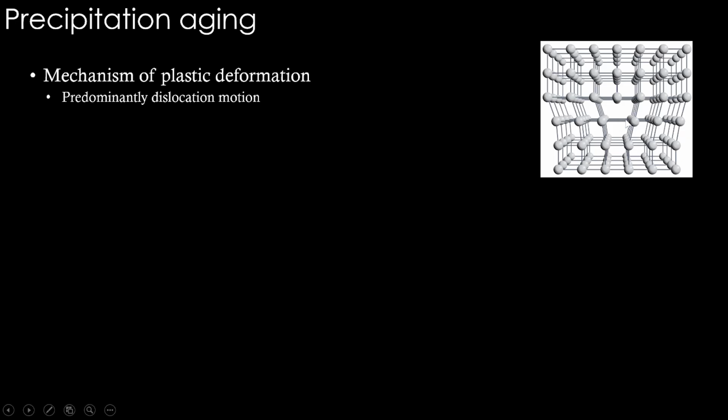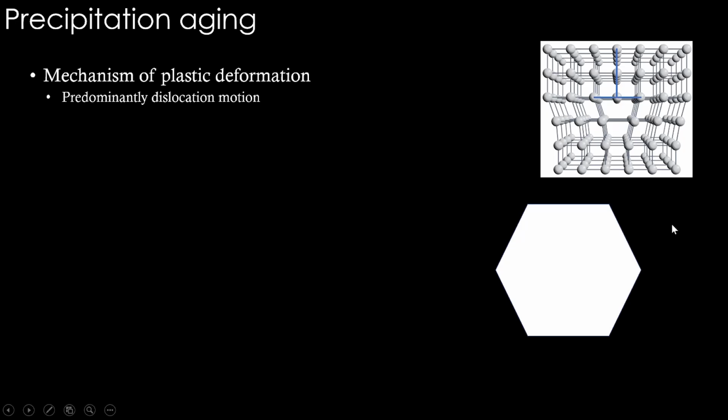And when we talked about dislocation pipe being a faster diffusion path in one of the previous classes, this area is what we have been talking about. This is a dislocation pipe, and this inverted T sort of thing is used to indicate the dislocation. So in a crystal, if I take a grain like this and if I put an inverted T kind of thing like this, it's a dislocation, and if it moves, then the material deforms. It moves within this lattice. Within the crystal it moves, and there are certain specific planes on which it will move.